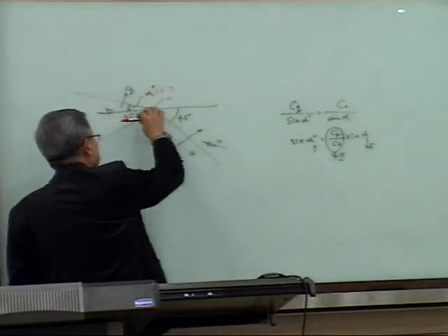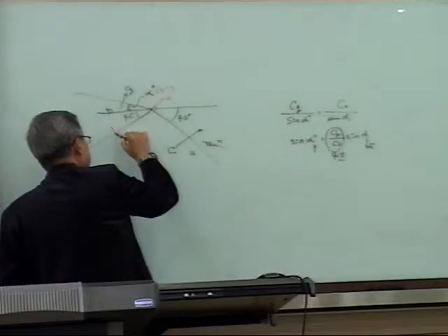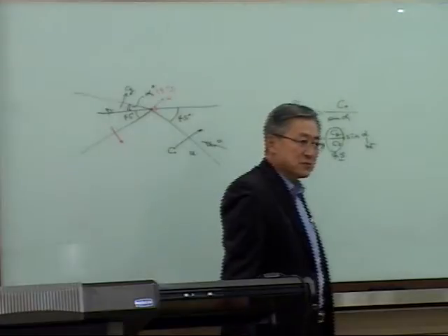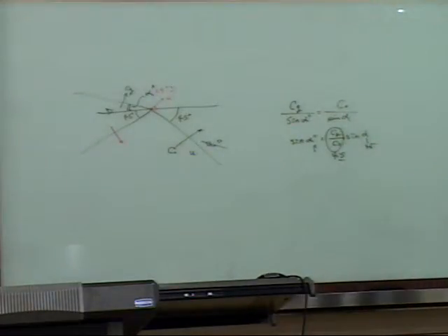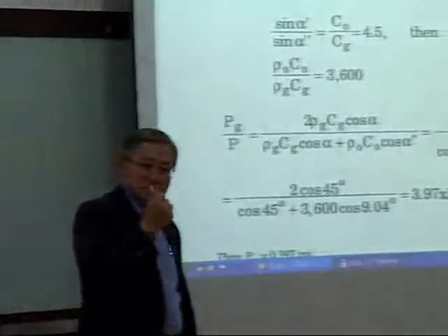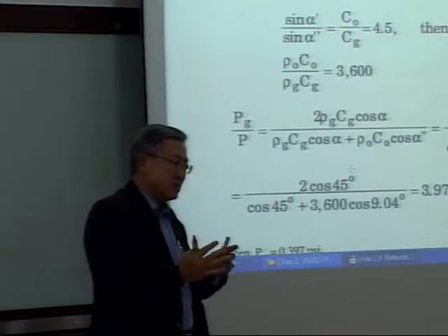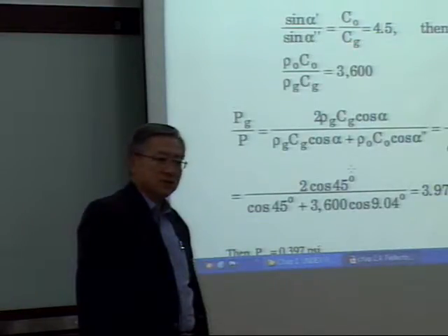And there will be a reflection wave coming down, which is called what wave? Surface reflection wave or rarefaction wave. Have you heard? Yeah. Which happens to be the tension wave, you call. What does it mean, tension wave? Rarefaction wave. What does it mean, rarefaction wave? Which is the wave pulling the water particle. So it's no longer a compressive wave, but it's a tensile wave.